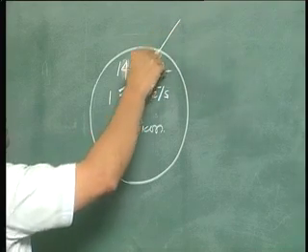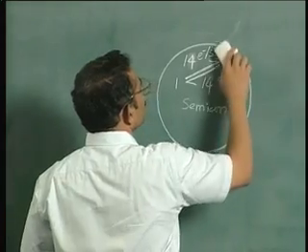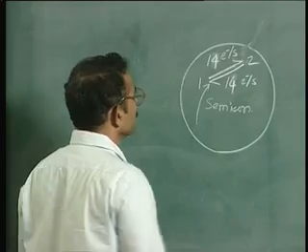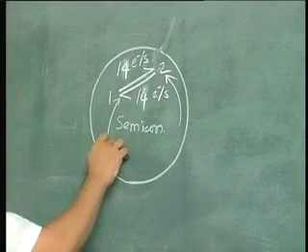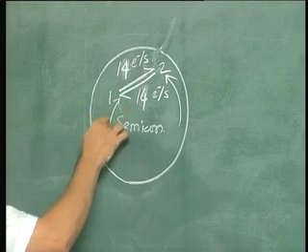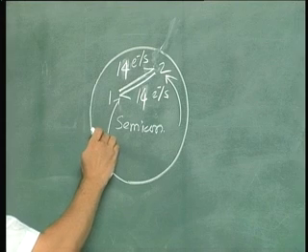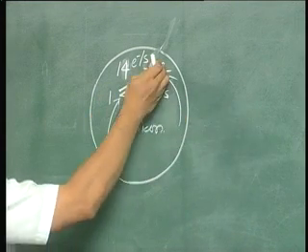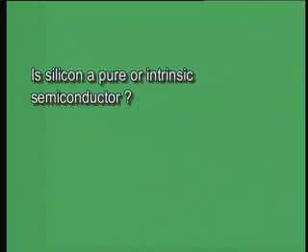Somehow more electrons are coming in from somewhere, maybe from outside or maybe from inside the semiconductor, from some other place electrons are coming to this point as well as to other points. Now there is no reverse process for this particular process. So there is a net movement of electrons from some point to point 1 and some other point to point 2, and there is no corresponding inverse process. So that is why this is not a case of equilibrium.